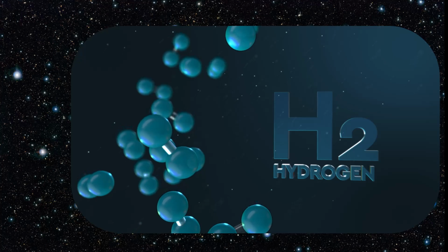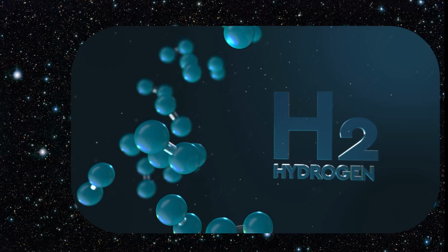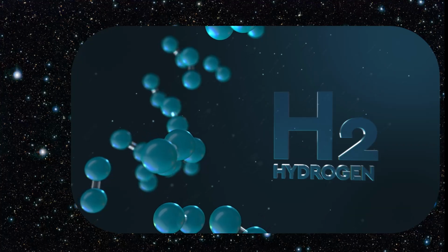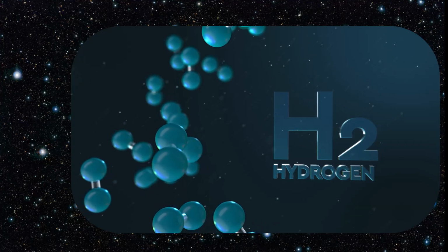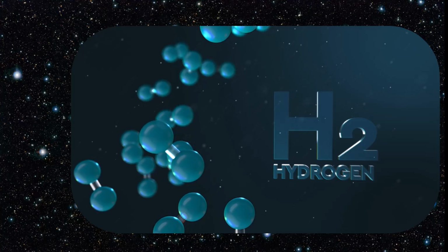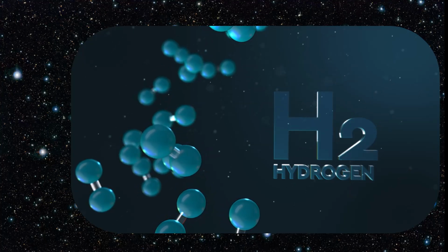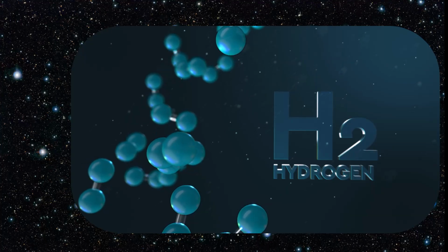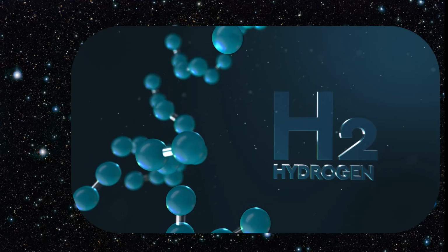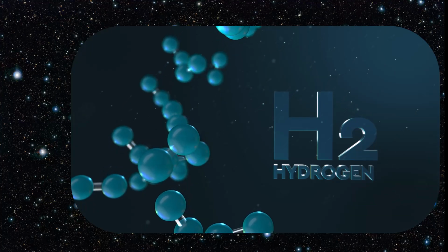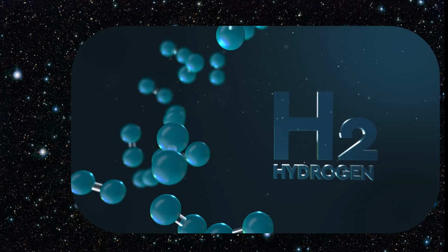Knowledge of these hydrogen damage mechanisms will be invaluable to the ASME B31.3 subject matter expert in the coming decade, due to all of the attention on hydrogen as a new and valuable energy source. The different mechanisms all depend on ion migration to affect the steel, but different mechanisms relate differently to hydrogen formation, ion life, and hydrogen ion migration to the associated damage mechanism. So let's review these different hydrogen damage mechanisms.